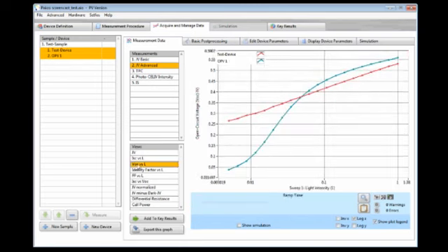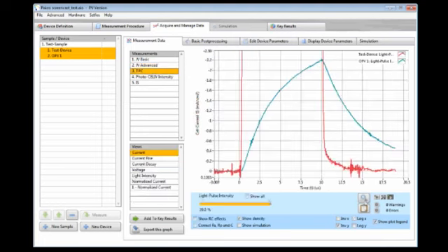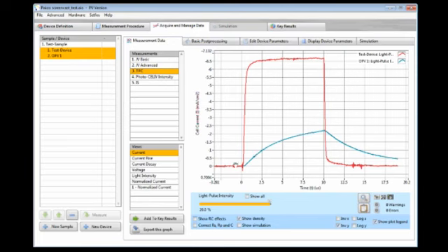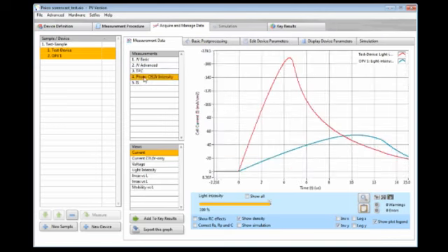For example, we can look at VOC versus the light intensity, and we see that the microcrystalline silicon solar cell here has a very straight linear behavior with the light intensity in log, and the organic solar cell here has a different behavior at low light intensities. We can also look at the transient photocurrent here and see that the organic solar cell, the rise time here is much slower than in the case for the microcrystalline silicon. Also in PhotoCELIV we see distinct differences.